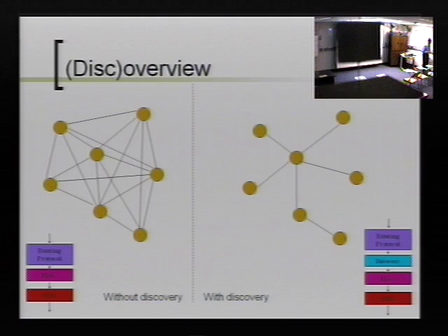Yeah. Do you think that you're adjusting transmission power? So there are two forms. One is reducing the transmit power to control the number of neighbors. The other is even at a certain transmit power, we can still reduce the number of neighbors we're interacting with. So we can only consider a subset of neighbors as useful. So let's say if energy is a consideration, you can talk to only your nearest neighbor, for example. Okay.